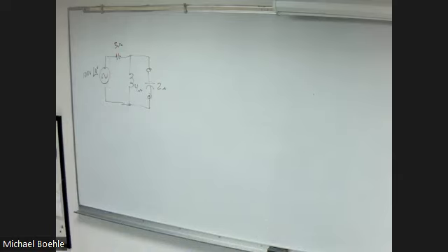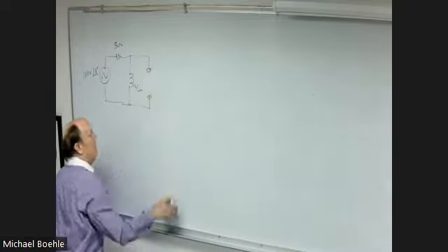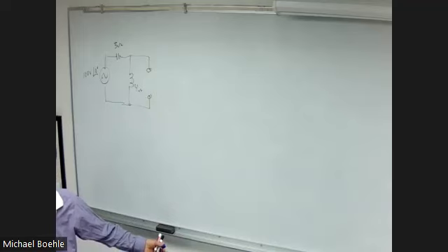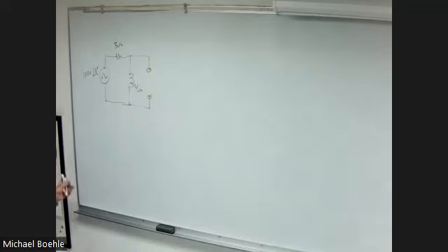All right. So 15 and 34 use the same circuit. One is finding Thevenin and one is finding Norton. The first thing to realize when you do Thevenin is what? That's gone. So we're looking for the open circuit voltage between those 2 points, which is simply going to be the voltage across the inductor. Which is pretty simple here, right?